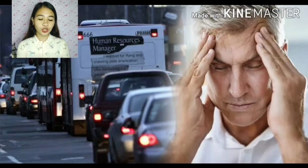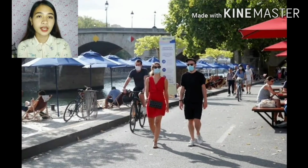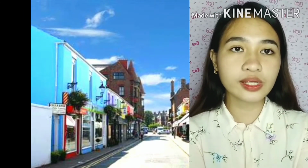Traffic noise and vibration must also be considered due to the number of vehicles using the road, may it be heavy or not. In fact, vehicle vibration may also damage buildings' fabric as well. Pedestrian, cyclist, and community effects in terms of increasing the journey time and breaking the links between them. The services or facilities that they are using every day, like their workplaces, schools, and shops, are also evaluated. And lastly, the policies and plans compatibility with the highway development plans at local, regional, and national level.